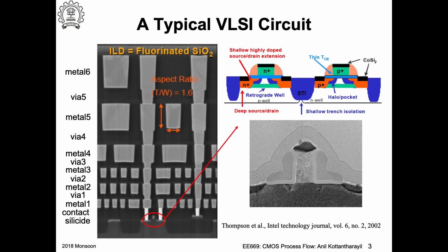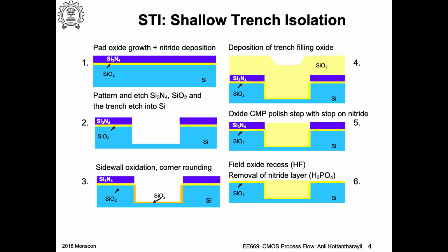Okay, and above the transistors you see this kind of rectangular blocks that are going up many layers. So in this you can actually count 6 layers, and these are metallizations for connecting these transistors together to make circuits. And here you see how we start the processing of the transistors, and the process steps are actually shown using 6 figures. So you can see these numbers 1, 2, 3, 4, 5, 6 that indicate the sequence.